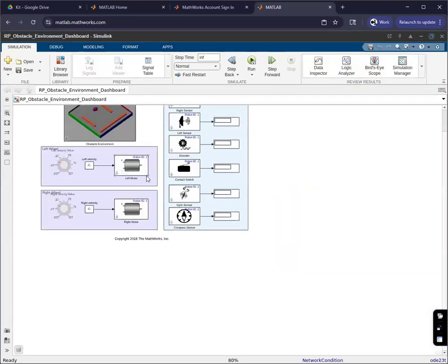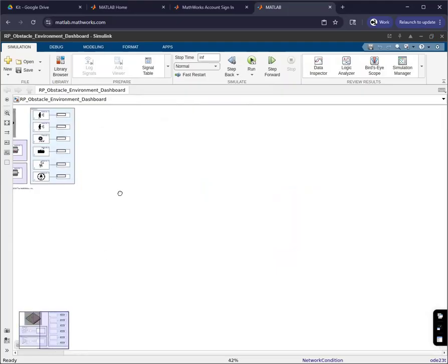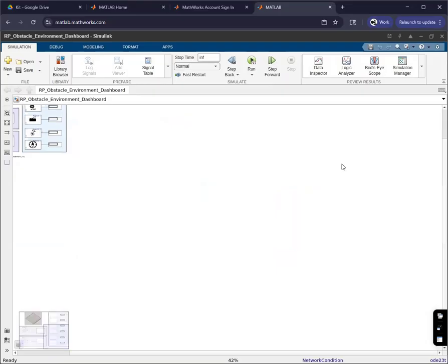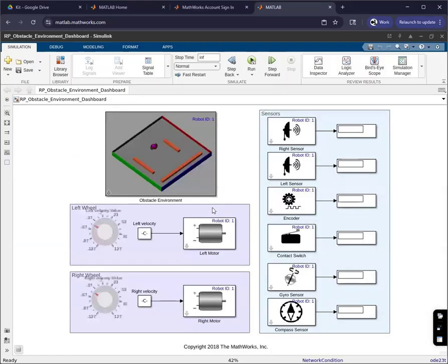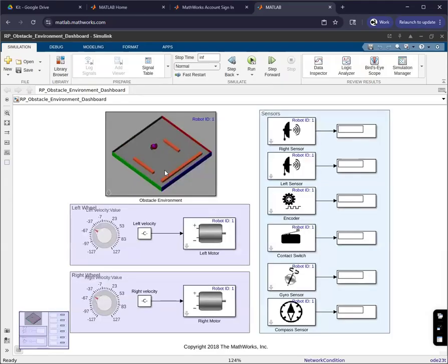And then this is right now zoomed way out. If it was off the screen partially or zoomed anywhere, if I click anywhere in this canvas empty space and hit the space bar, it will auto fit everything in that working space to be able to see what exists there. So you don't have to work on zooming and moving stuff around, just hit the space bar.